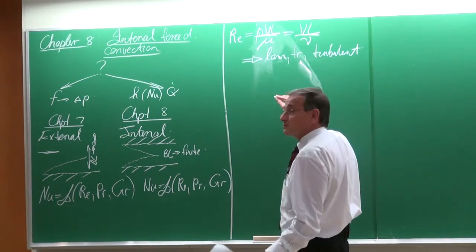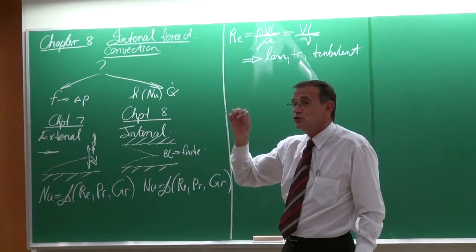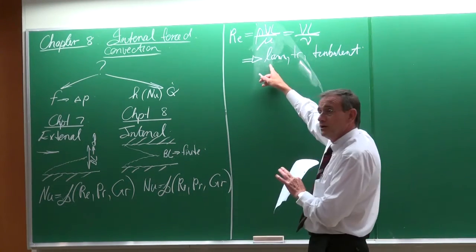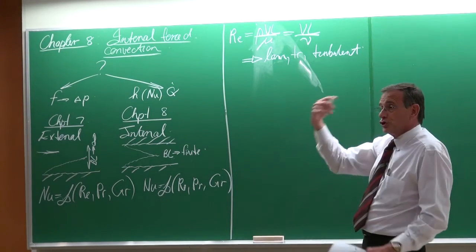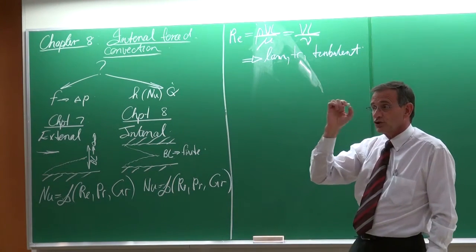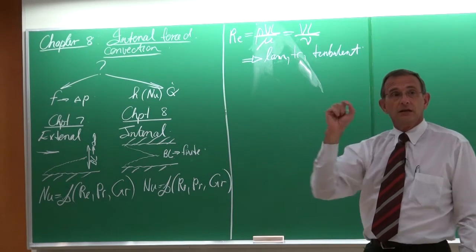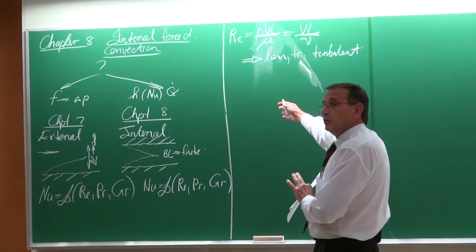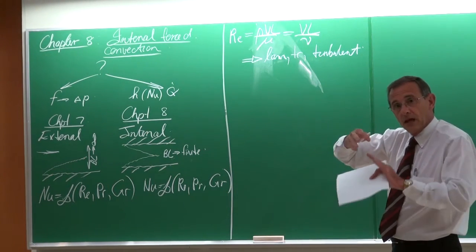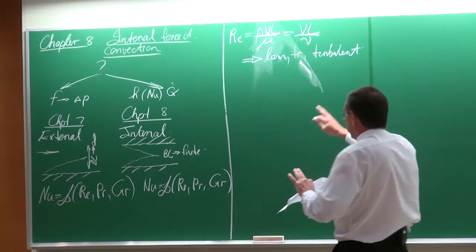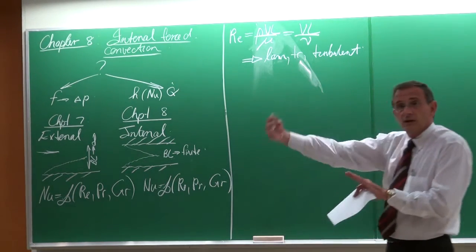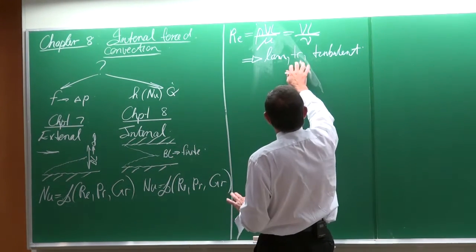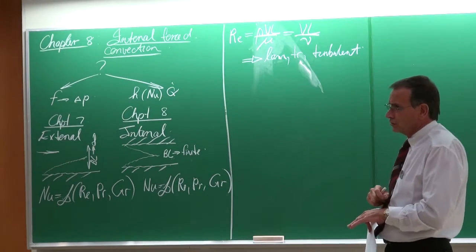There is no specific Reynolds number which is being used for all geometries in terms of telling us when the flow will be laminar or turbulent. For a tube, not internal flow, but for a circular tube, it occurs when the Reynolds number is 2,300. Over an aeroplane wing, it will be another Reynolds number. But the Reynolds number in general tells us, obviously with empirical information that we need from experiments, if the flow will be laminar, in the transitional flow regime, or in the turbulent flow regime.